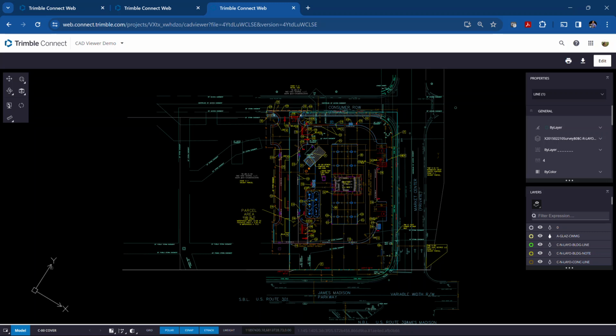So north is actually in the direction of that Y direction or Y coordinate, and then your X direction, which would be your east, is pointing down slightly at a 45-degree angle. But it gives you an orientation to where north resides within your project if your project is on a coordinate system like a state plane system, or other geodetic coordinate system.